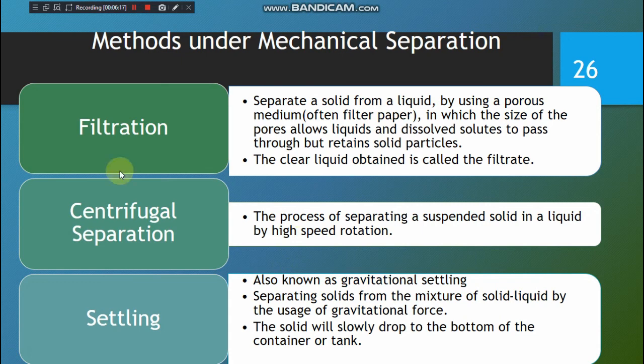Based on this statement, it can be understood that there is not much difference compared to filtration as mentioned earlier, because this method also deals with heterogeneous mixtures, which are solid-liquid or solid-vapor gas. So the only difference is concerning the cause of flow: pressure difference is applied for normal filtration, but obviously centrifugal force is used for the centrifugal filtration type.